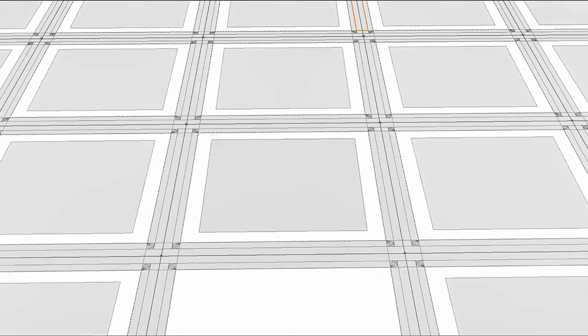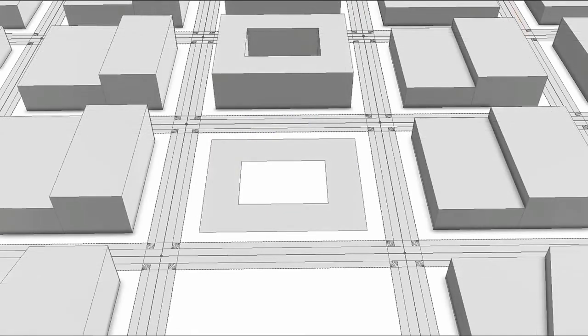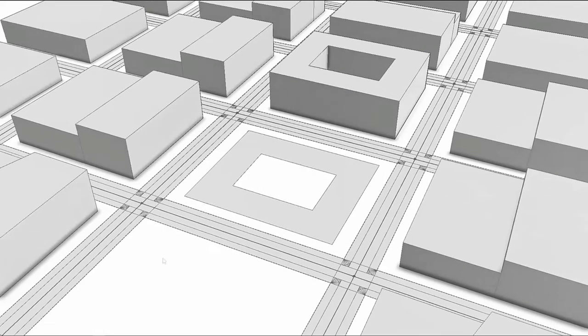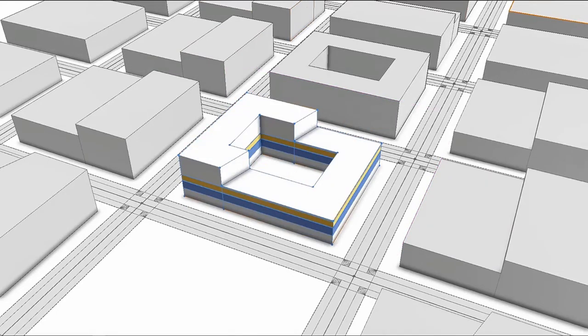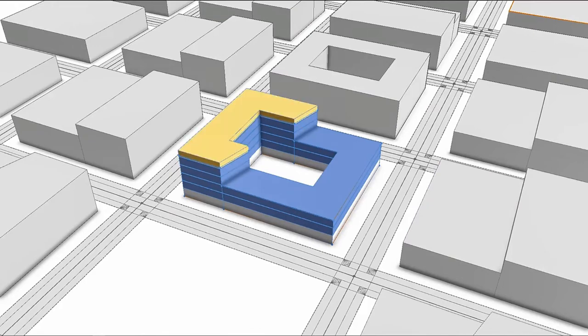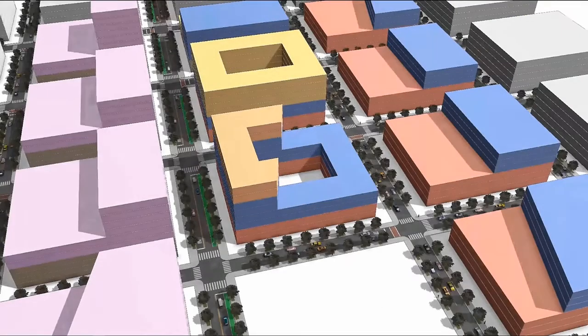We've greatly improved the drawing tools in CityEngine to actually help you create these designs, enhanced the snapping, allowing snapping to streets, adding guidelines that snap to streets, improved the ability to draw holes and cut shapes from shapes. So you can actually do Booleans between two different shapes. The ability to align, for instance, guidelines to adjacent features. So I've aligned it to an angle on that adjacent parcel and then brought that angle across into this newly proposed building. And then, of course, I can apply rules to it to enhance the proposed design, maybe split it into floors or add architectural detail.